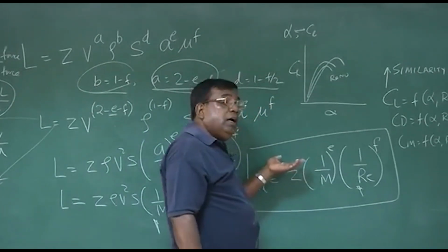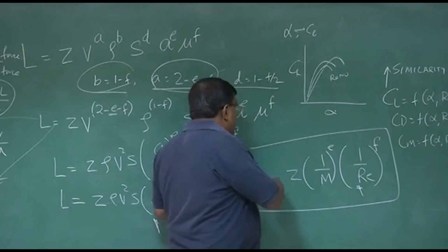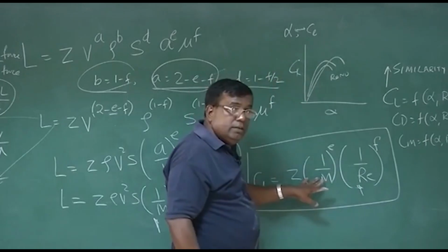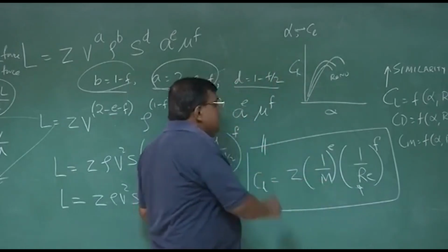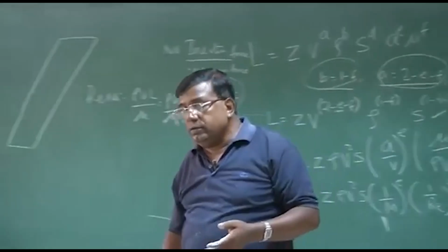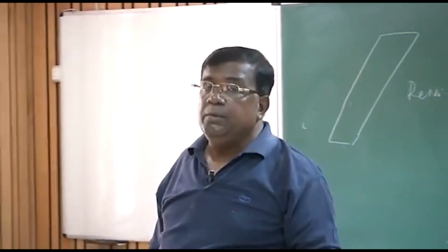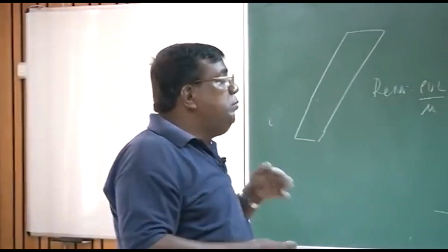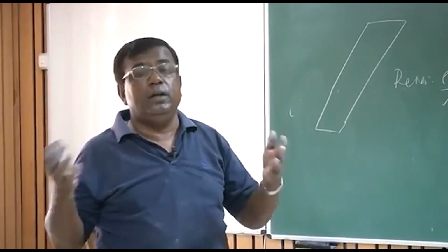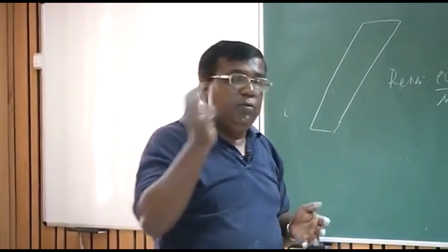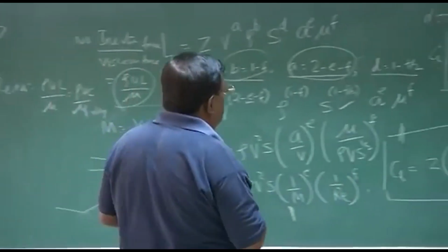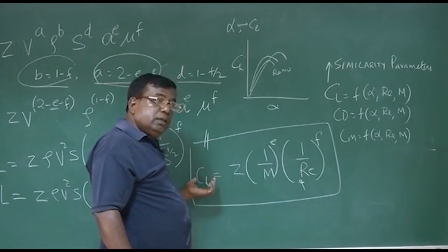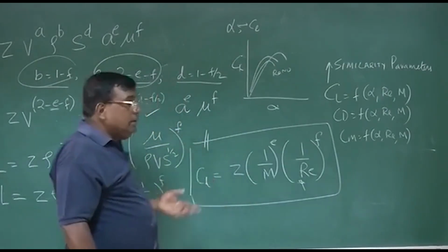I need to ensure that the models are geometrically similar, and we are able to take advantage of this analysis. And that is why CL, CD, CM, all these things are sometimes referred to as similarity parameters. Okay? So dynamic similarity in terms of flow, and similarity parameter means that for a geometrically similar airplane, if you have ensured that it is dynamically similar, I can get a meaningful value of CL through testing by doing scaling. Okay, thank you.